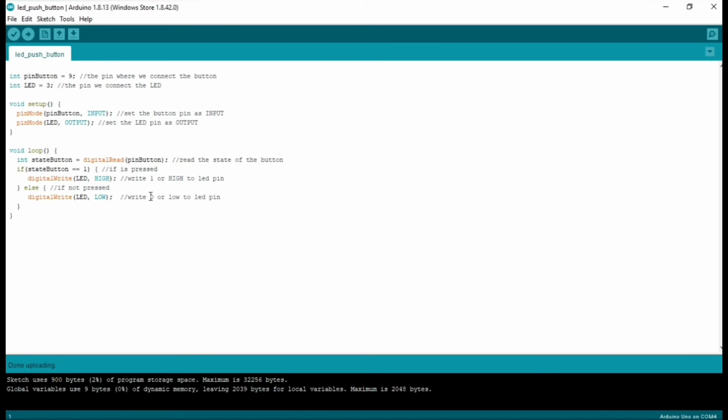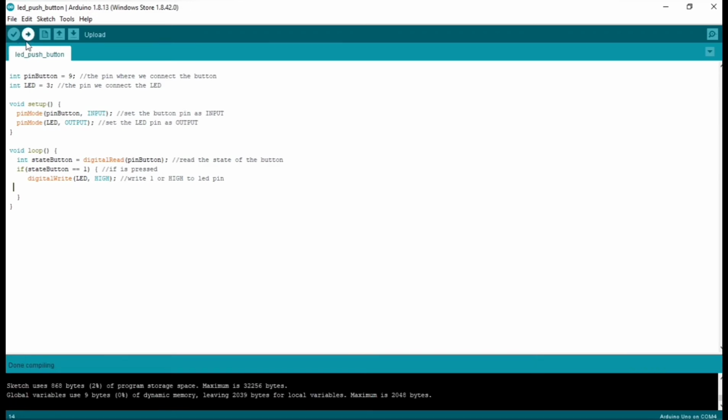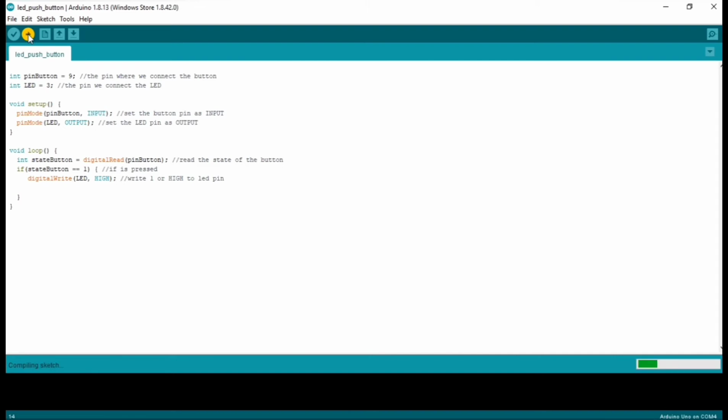For case 2, we will just delete this else statement, so that our LED will continue in the on state even if we release the push button. So let's delete this one. Then let's compile it. Okay, you see that there is no error. So let's upload it. Okay, it's done uploading also.